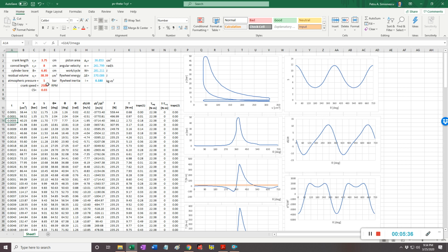This is where the time gets calculated. When I have the corrected angle, contiguous, going all the way to 720, turn to radians and then divide by angular velocity, that gets you the time. Okay, so distance divided by velocity gets you time. Likewise in rotational motion. The equations for S as a function of theta, see the notes equation as so, velocity of S is a function of theta, acceleration of S a function of theta.